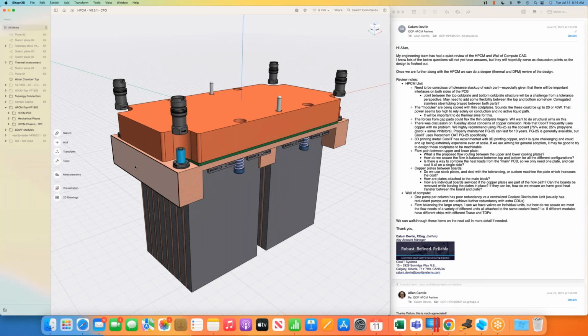And the idea here is that we would control the flow through every module, because every module will be burning a different amount of power, and the outlet of the water would always be in the region of 65 C, so that we're compliant to the energy reuse temperature requirements. So different modules burning different powers would have different flow rates through them.